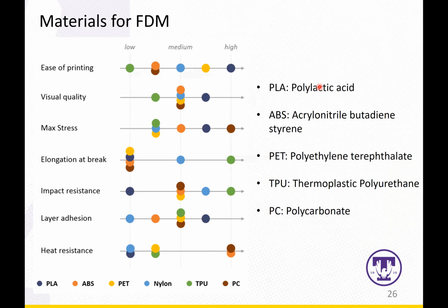I don't know why, but it turns out I didn't heat up the platform, and the bonding between the first few layers and the platform is not good if you do not heat it up. And it turned out the printed part slid on the platform, and it ruined the whole printing process.